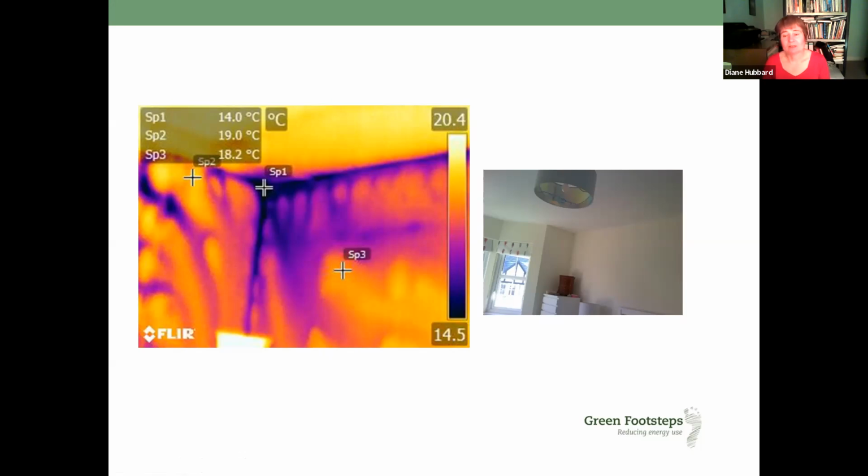And plasterboard should be edge sealed, so around the perimeter of each board as it's fitted, it should be sealed all the way around the edge. Now it's quite difficult to do when you've got things like plug sockets and stuff. But what we can see in this image is what's happening behind it.